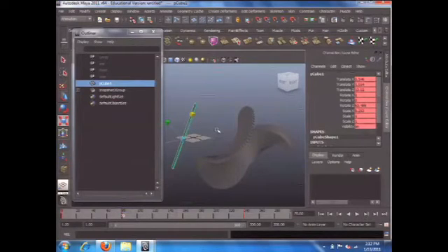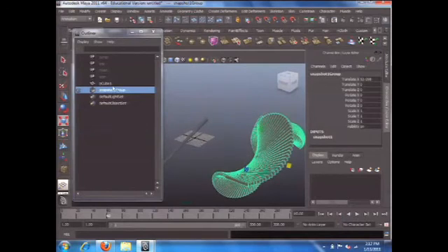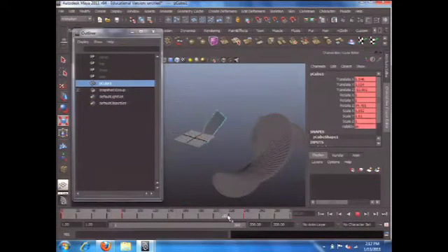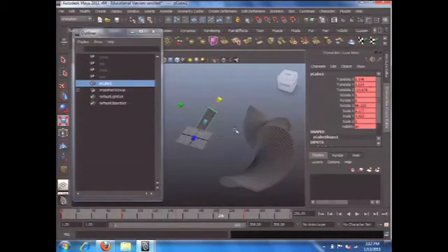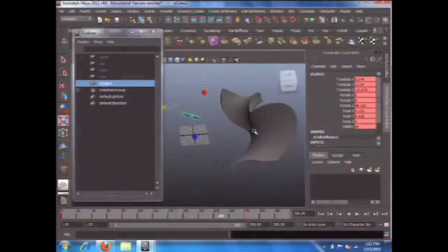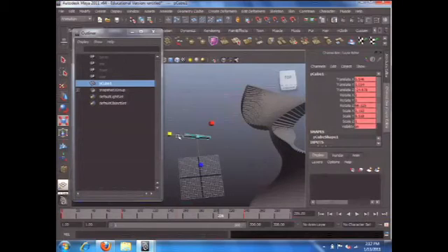As soon as you hit S to keyframe the animation, the animation will be refreshed, and this object will update in real time. Let's do this one more time. I click this cube. I go to another frame. For example, here, let me change another scale. So I drag it to make a smaller scale, and then use S to keyframe. See what happened? It updated right there. Scale, S, it updates. All right, so it's very, very dynamic.